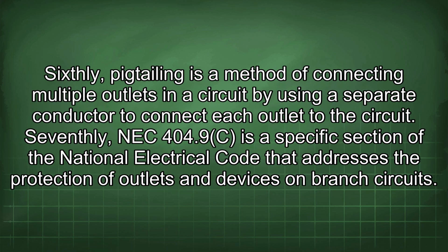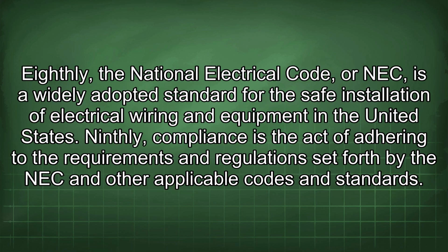Sixthly, pigtailing is a method of connecting multiple outlets in a circuit by using a separate conductor to connect each outlet to the circuit. Seventhly, NEC 404.9c is a specific section of the National Electrical Code that addresses the protection of outlets and devices on branch circuits. Eighthly, the National Electrical Code, or NEC, is a widely adopted standard for the safe installation of electrical wiring and equipment in the United States.